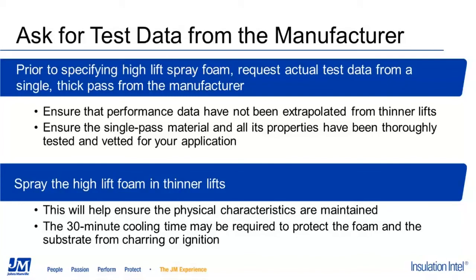Additionally, you can spray the high-lift foam in thinner passes. This will help control the density of the foam, and it will also help to ensure that the physical characteristics are maintained throughout the entire sample. If this technique is chosen, please consult with your spray foam manufacturer and their documentation because a 30-minute cooling time may be required to protect the foam and the substrate from charring or ignition.